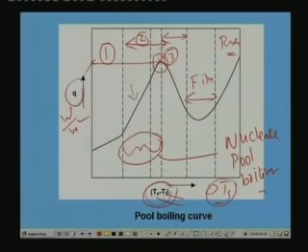If you increase the temperature difference beyond this, then the heat flux has to fall. This point is also known as the burnout point, which you must have studied in the design of boiling. As I said, refrigerant evaporators are designed to operate in the nucleate pool boiling region, so the correlations are available for this particular region.